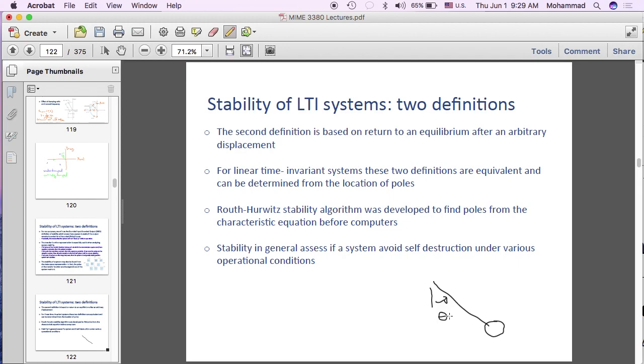Why don't we look at it right now? You can see the poles of this system. You remember we came up with two linearized versions of the differential equation? Do you remember that? Now, if you look at the poles of those two systems, you would see that one of the two poles for the unstable equilibrium is to the right of the imaginary axis. If you have your notes, go back and take a look.